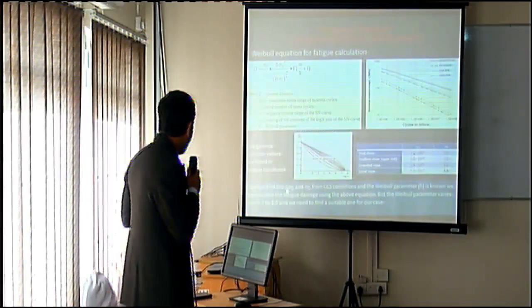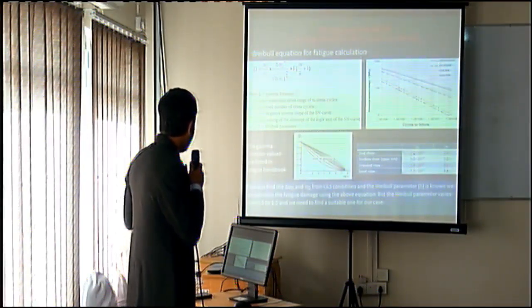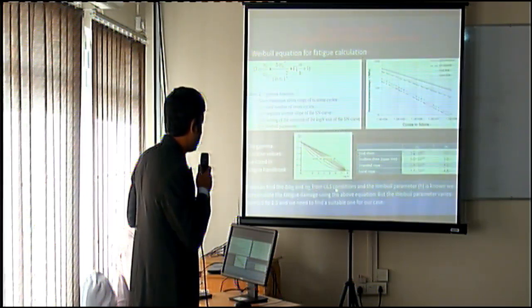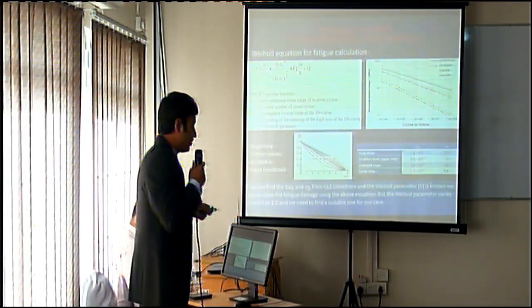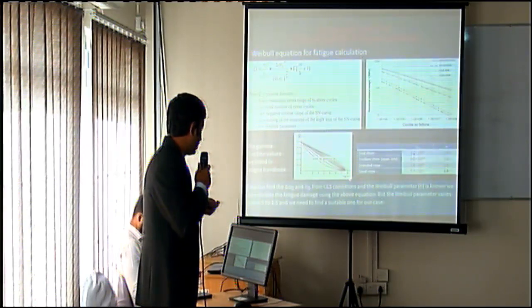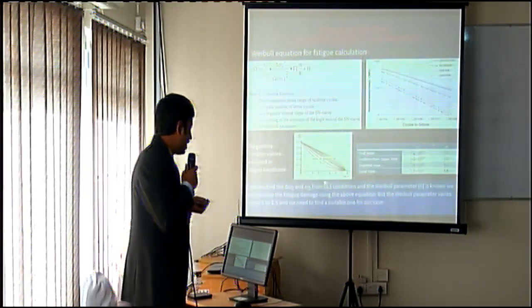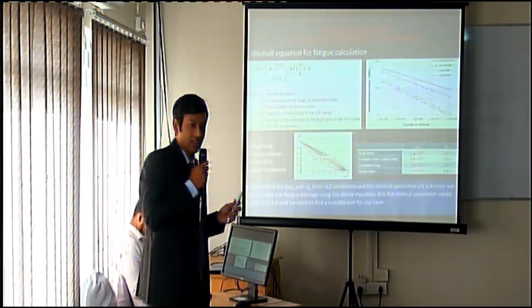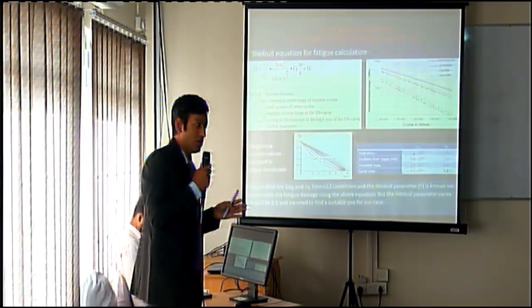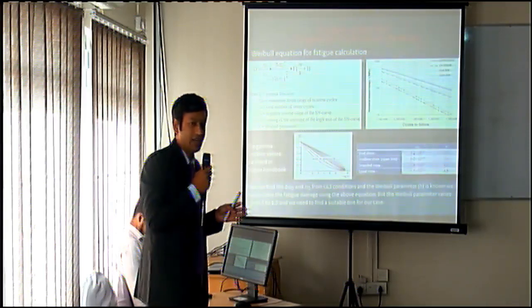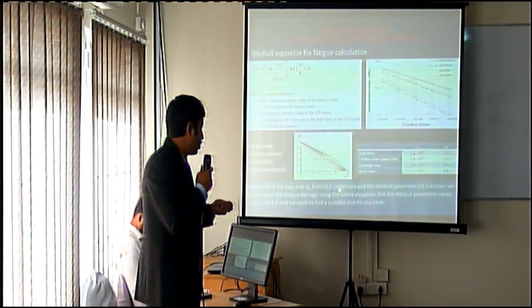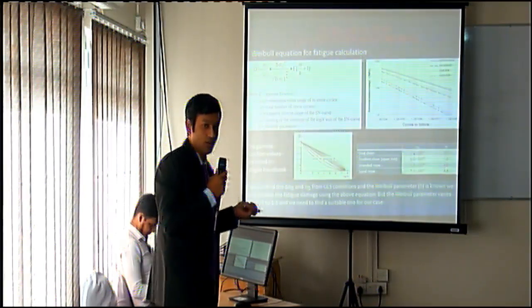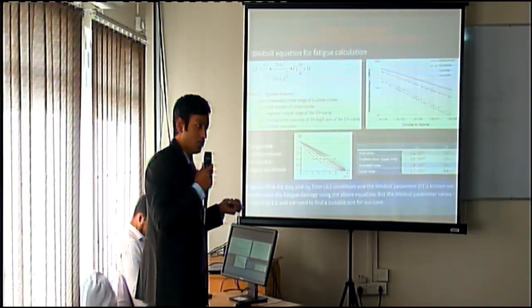Here, we can find the sigma, this stress value, and also the number of stress cycles for the ULS condition. Let me clarify what the ULS condition means. This is the ultimate limit state, meaning that every structure, like a vessel, modules, or whatever it is, must be designed according to this ULS condition. So even if you don't want to do the fatigue analysis, you must do the ULS design condition. You need to fulfill that.